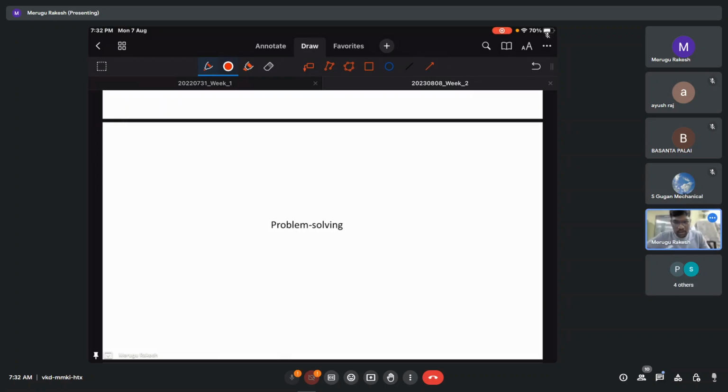Yeah, hi. So let us continue with the problems. Before that, I will answer this question, sir. How to determine the diameter of the riser when only the riser height is given? They will mention whether it is the optimum riser or not. If it is optimum, you can take diameter equal to height and solve the problem. That is one way of doing it. Otherwise, there is no way to find the diameter of the riser.